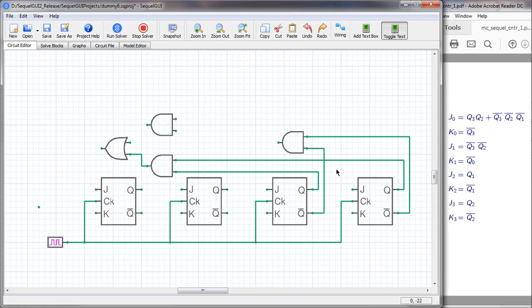One question that comes to mind is whether there is a crossover here or whether these wires are actually connected. The way to check that is to click on the wire, and that shows the complete path. So in this case, this wire is simply crossing over this other one. It is a good practice to use these connectors to indicate connections. So for example, if there was actually a connection over there, then we could have placed the connector over there and used that for our wiring.